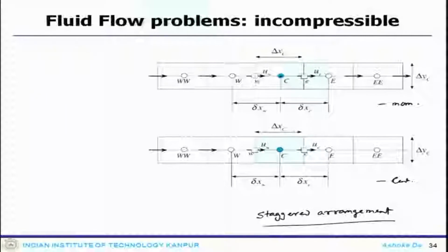What helps is that when you calculate the fluxes, you do not have to do any interpolation, straight away you can get the value, and the pressure field is stored at the cell center. That way one can avoid the checkerboard situation which appears in a system.